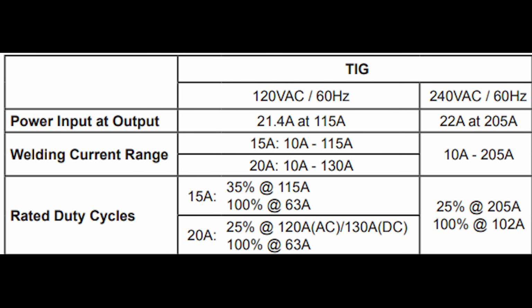Now, I'll be honest, that TIG 200 that I started with, I never actually hit the duty cycle on it, and I welded a ton, but that was an okay piece of equipment. If you buy a cheaper 200 amp class machine off of Amazon, you can pretty much bet that you're going to hit thermal overload or the machine's going to shut down.